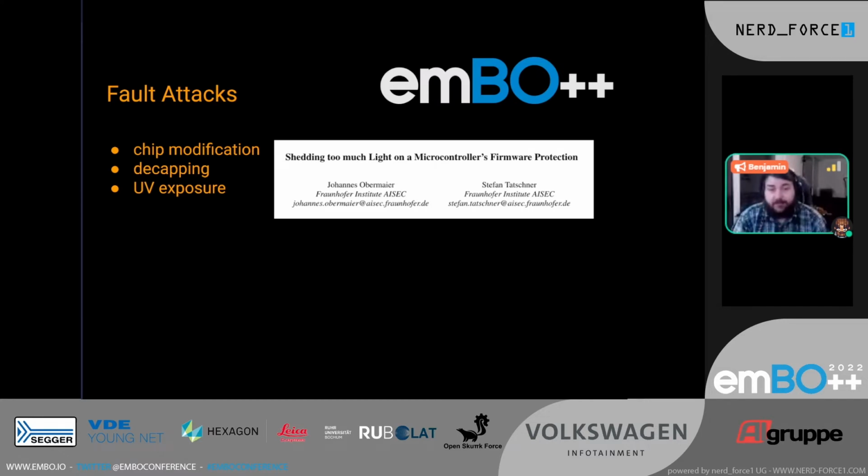And the third state is no debugger access at all, so full lockdown. These 3 states are stored in a single byte in the configuration region. One byte value means no debug protection, one byte value means full debug protection, and any other byte value means medium debug protection.